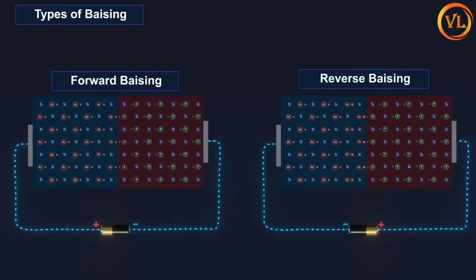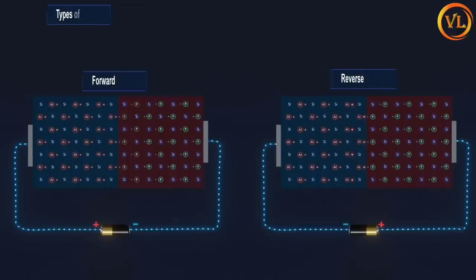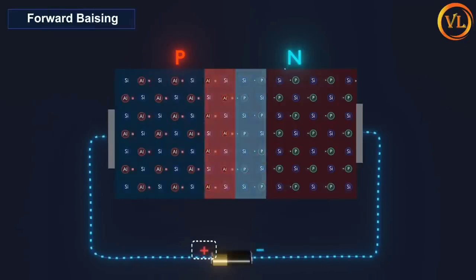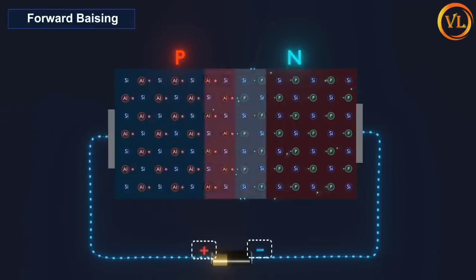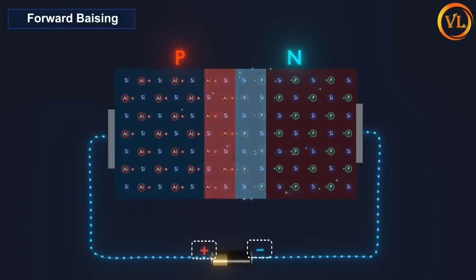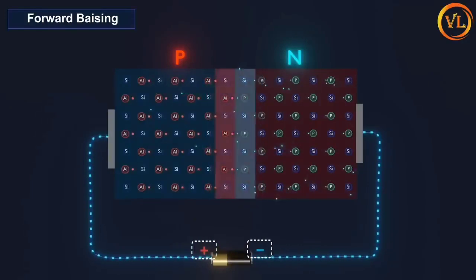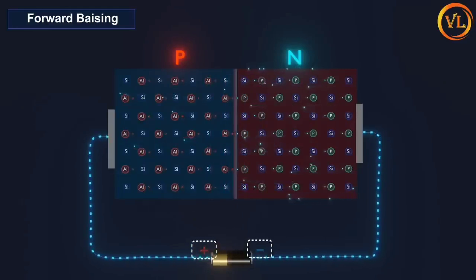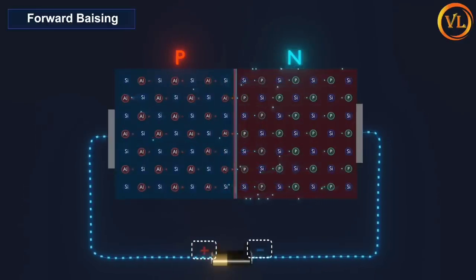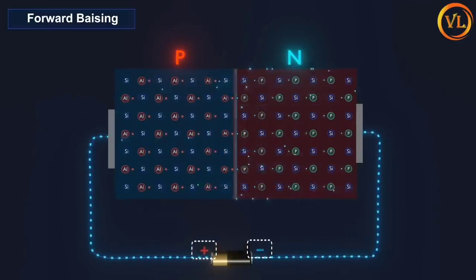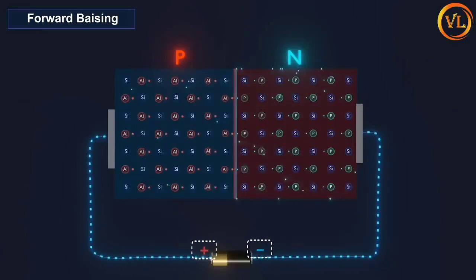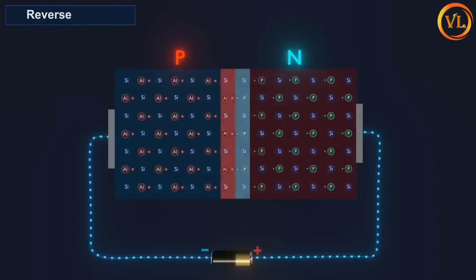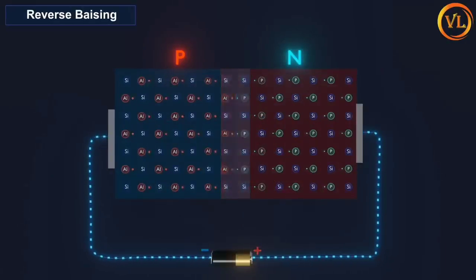The slope of the PN junction diode in forward bias shows the resistance is very low. When a forward bias is applied to the diode, it causes a low impedance path and permits the diode to conduct a large amount of current. This current starts to flow above the knee point with a small amount of external potential. The potential difference across the PN junction is maintained constant by the depletion layer action.